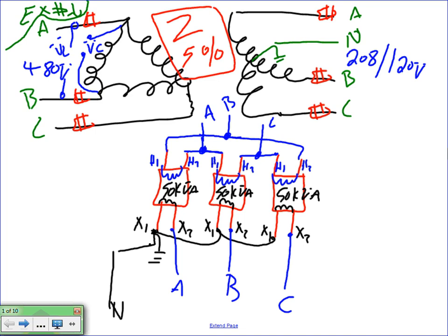When we deal with industrial buildings, guys, there are two types of transformers you can buy. Three-phase. Now we're talking about three-phase. You can buy a big fat three-phase transformer, that's one big box, primary, secondary, or especially in the industrial, you can buy three single barrels, three single transformers, and hook them up to give you a three-phase system.